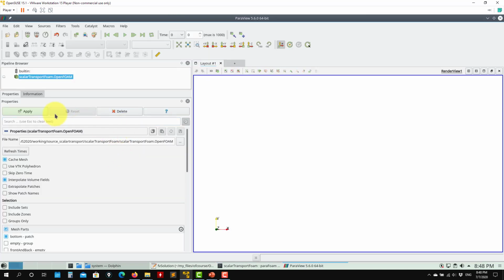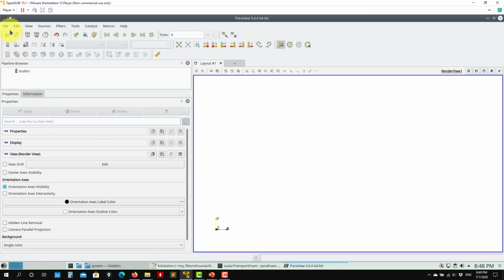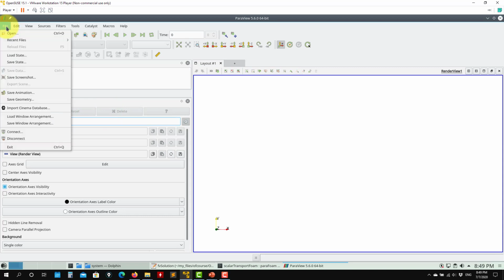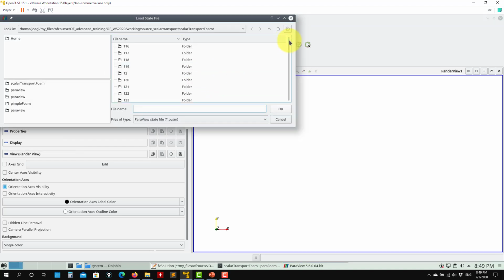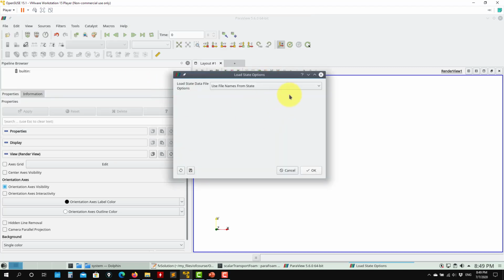So the limited linear that we are using here is a bounded variant of the linear method. In the case that you have some strong gradients, if I recall, it will default to upwind. So it's a pure linear plus the upwind for strong gradients.